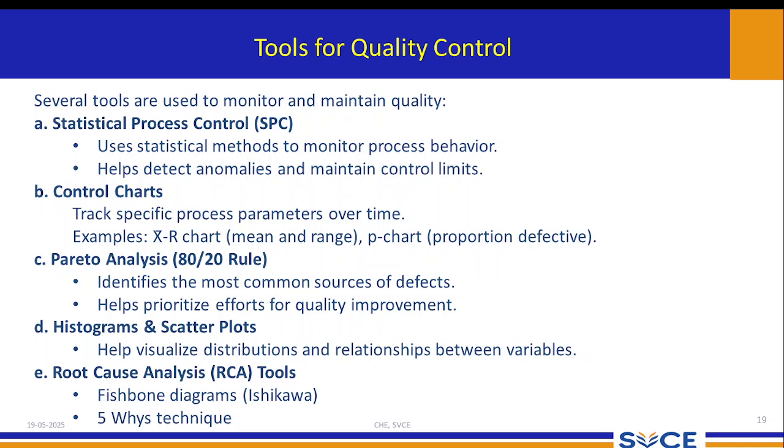So that is the main purpose they are giving here. Distinguish the causes from symptoms. Ensure you are identifying the underlying causes and not just symptoms of the problem. Work backwards: review your answers to ensure you have correctly attributed each why to the previous one. The 5 Why technique is a simple yet powerful tool for root cause analysis, helping teams in quality control to pinpoint and address the core reason for problems effectively.